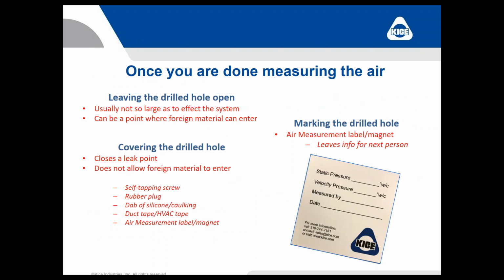And then, wrapping this up, once you're done measuring the air, leave the drilled hole open. Usually it's not so large as to affect the system, but it can be a point where foreign matter can enter. Or you cover the hole. It closes a leak point. It doesn't allow foreign material in.